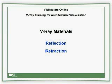Module 3, we're going to look closely at the material editor and see how we can simulate just about any material on Earth by controlling all the visual properties a material possesses. Materials are my personal favorite area of 3D to work with because to me it's the point at which objects come to life, and I really just enjoy working with all the great tools that VRay provides and seeing all the wonderful effects that just a few short years ago weren't even possible.